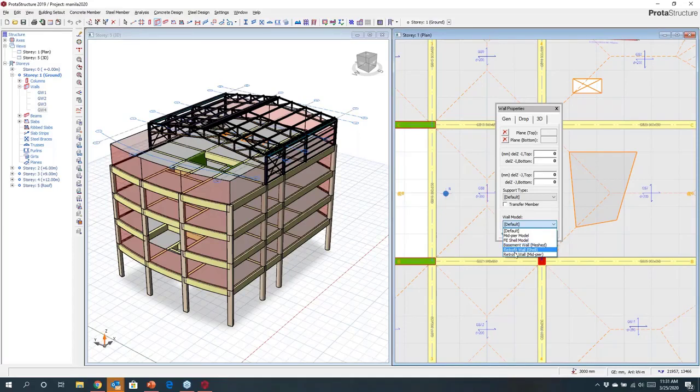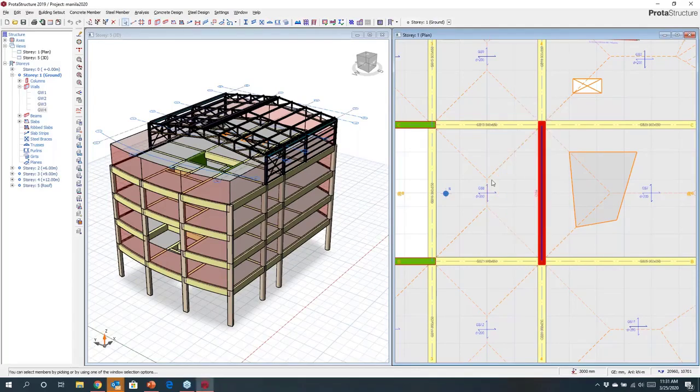within the software. You might also notice that we've got retrofit walls in here as well. So if you're wanting to upgrade an existing structure, you can also come in and define infill shear walls and design those within the building. So if you have an existing structure, you could model this. You can place infill shear walls within the model, and then you could, as a method for strengthening the building, suit the current codes of practice.